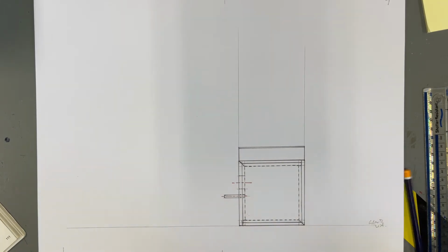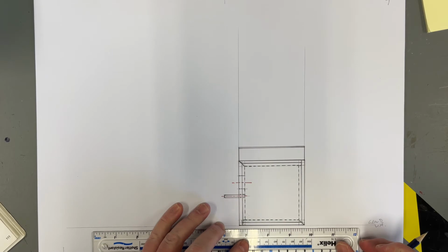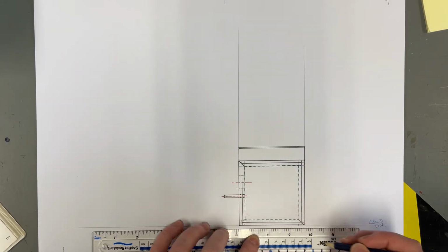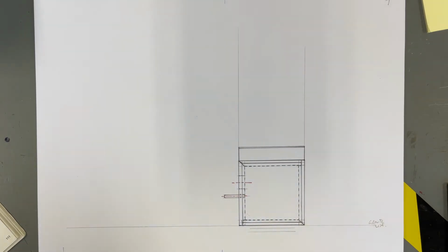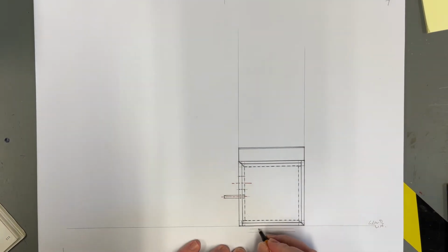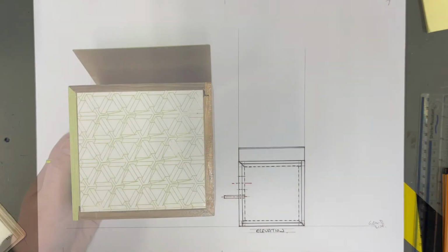Right, to finish off, underneath the view, we're going to just sketch in a little construction line here, a little construction line here, and we'll put in the view titles. This would be elevation. And the only thing left on that view to do is to put the dimension lines in, but I think we'll do that once we have all of the other views in place.